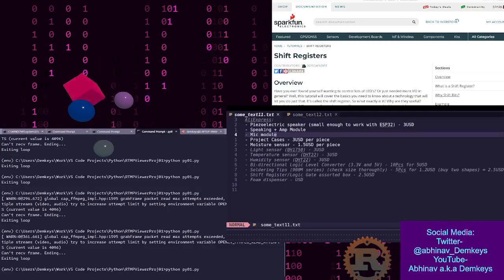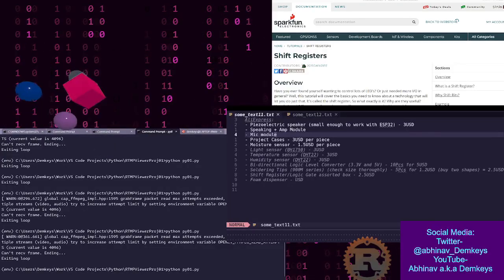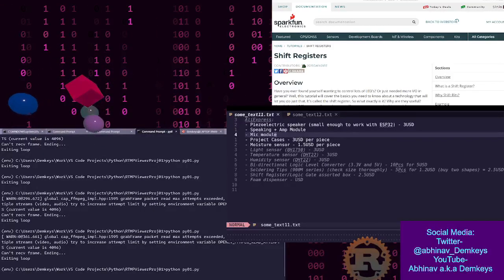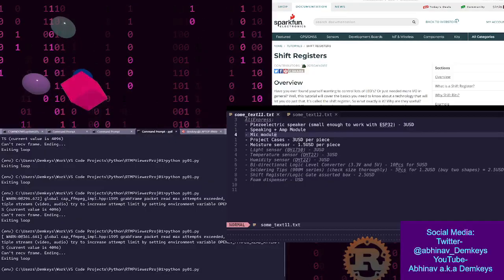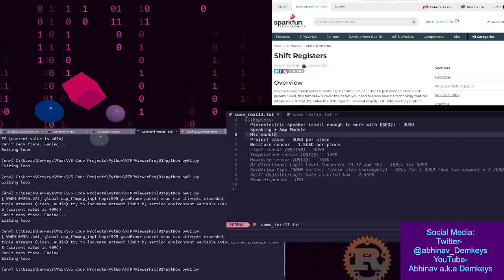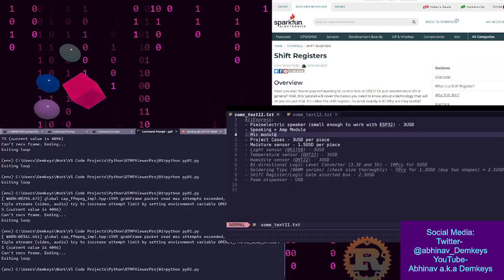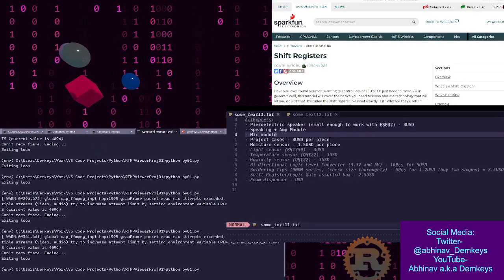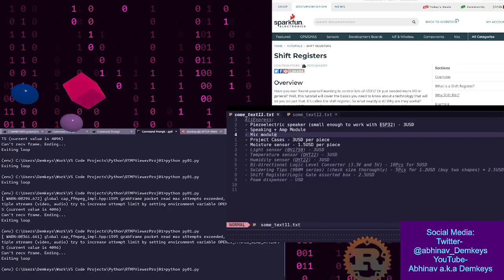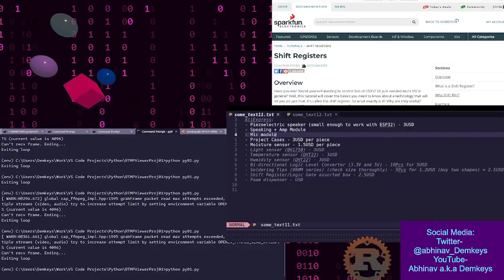Apparently, it includes a 128-bit wide register, and there's also a 128-bit data bus, and it has vector instructions, SIMD kind of instructions. SIMD is single instruction, multiple data, basically meaning that one instruction can operate on multiple pieces of data.